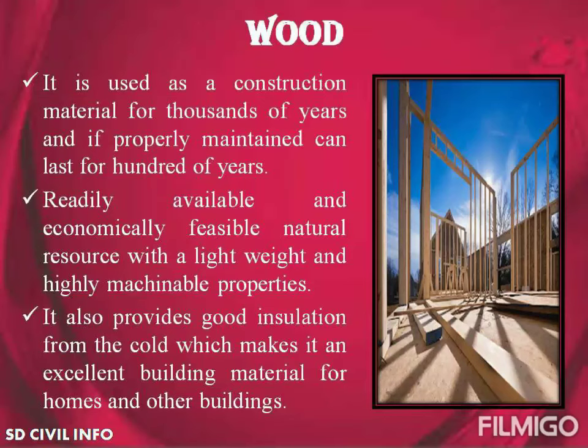First one is wood. I hope you all know that wood has been used as a construction material for thousands of years, and it is said that if wood is properly maintained, it can last for hundreds of years. Wood is a readily available as well as economically feasible natural resource with lightweight as well as highly machinable properties. Wood provides good insulation from cold, and this property makes wood an excellent building material for homes as well as other buildings.